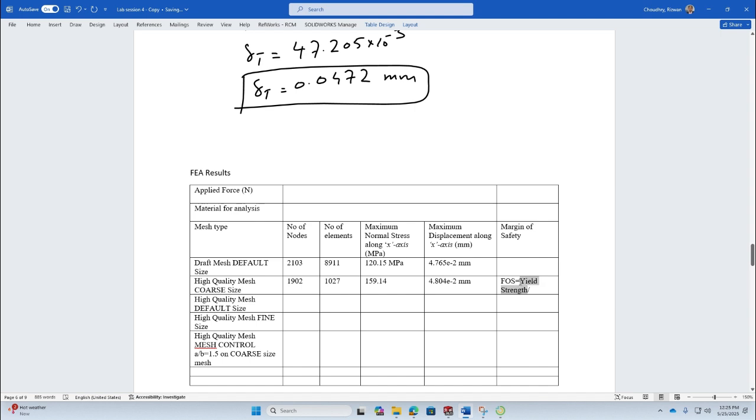No, because this is the margin of safety. Look, this is where you have to think about it. It's no longer allowable. It's about the actual maximum value of the stress, because the context is you are trying to figure out whether this is safe or not, or how safe it is, right? So this is the context of margin of safety. So divided by actual maximum